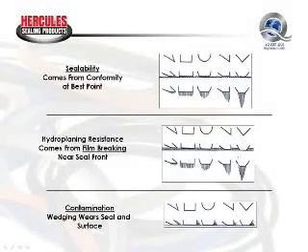Because the B lip actually conforms better to the sealing surface, it does a better job of breaking the fluid film that adheres to the seal or the sealing surface when the rod extends. So we have a higher degree of sealability from the B lip than we do from the D lip. You'll have a wetter surface with the D lip than you do with a B lip.